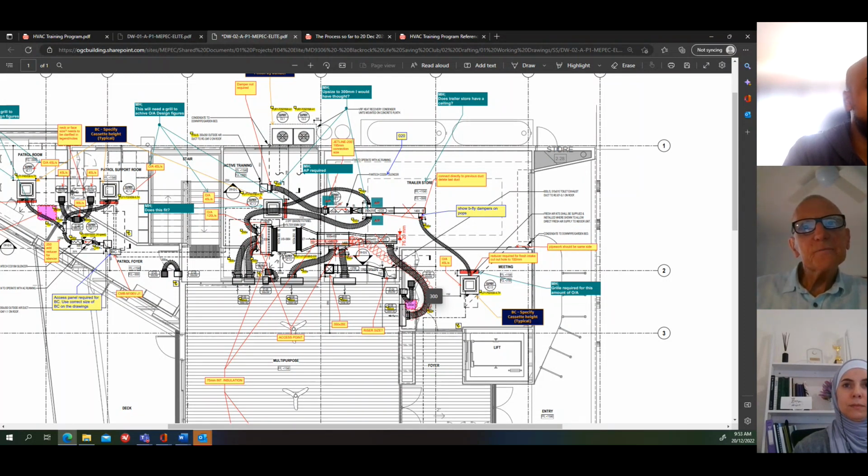This drawing also has sizes for flexible duct. Basically, everything is shown on this drawing that the guys on site need to install the equipment in position. You'll see that there's a dimension. It's a bit hard to see, but there's a dimension here, which is from this grid line, which will be marked on the site, to the side of that unit. So they can position it one way or the other, get it in the right position, and then install the ductwork from there, so it all fits in.